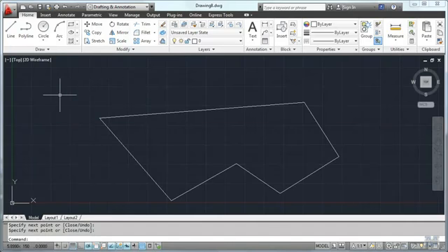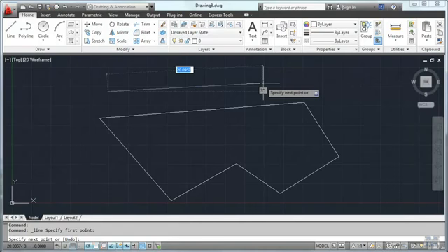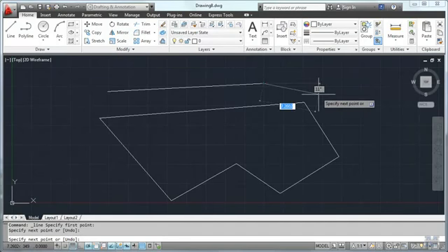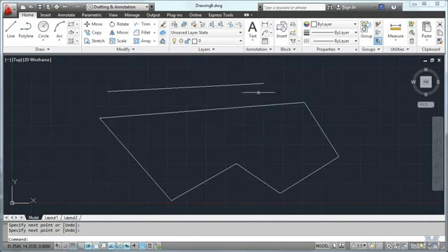Now in the old school software, or not that old I guess, actually using a mouse, if we did the line tool and left clicked and you right clicked at the end of a line, it would do the Enter key for you, but in this case the newer stuff doesn't. You can go into the settings and mess with that if you like that. We'll just left click Enter if you're doing it in that manner.